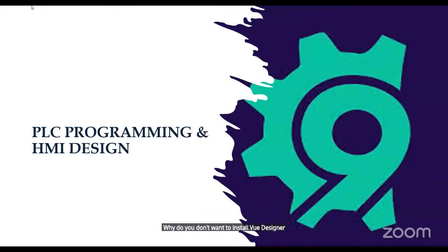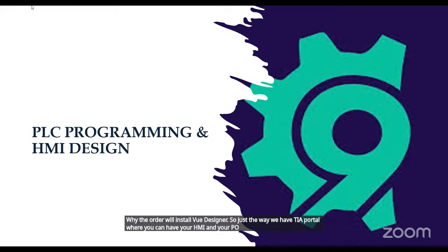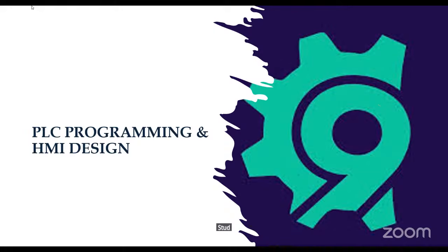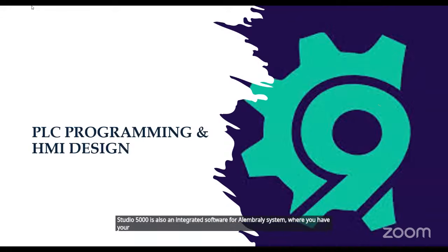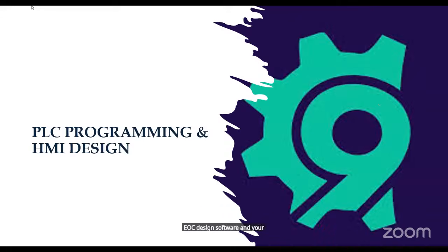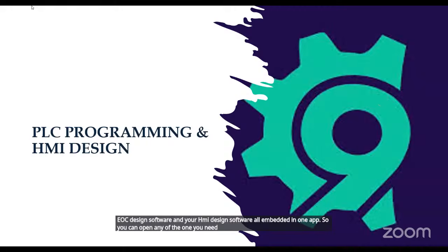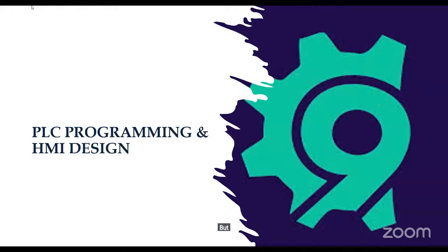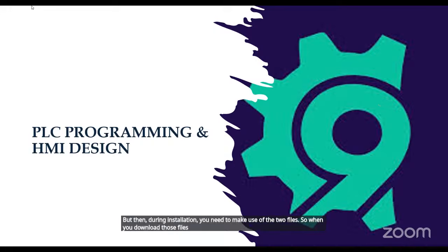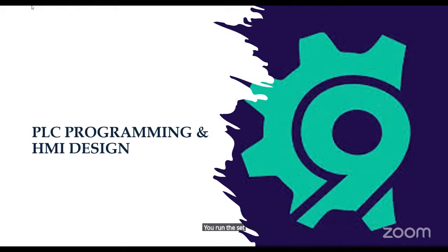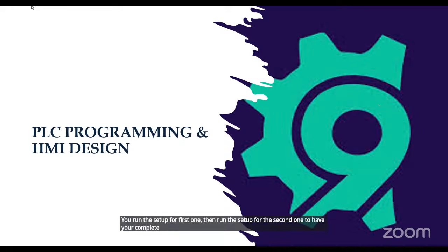So just the way we have TIA Portal, where you can have your HMI and your PLC designed from TIA Portal, Studio 5000 is also an integrated software for the Allen Bradley system, where you have your PLC design software and your HMI design software all embedded in one app. So you can open any of the ones you need from the Studio 5000 interface. But during installation, you need to make use of the two files. So when you download those files, you run the setup for the first one, then run the setup for the second one to have your complete Studio 5000 package installed.